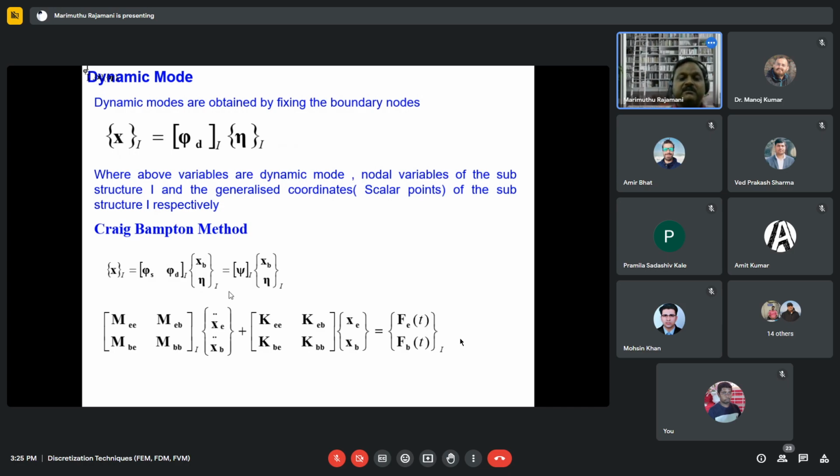The wing group does everything itself, and then they supply the interface matrices to one team, which gets interface matrices from different people, assembles and solves them, and provides the mode shapes of the whole interface portions.